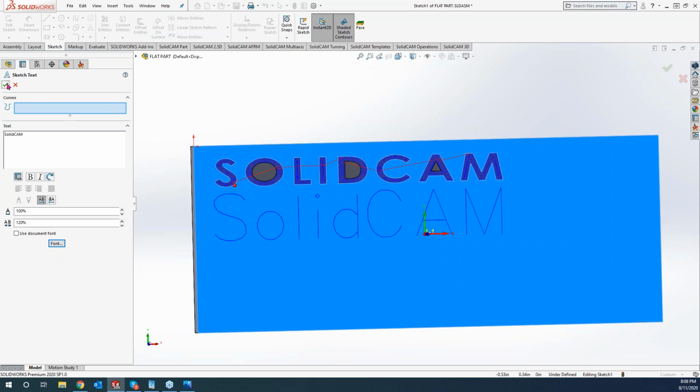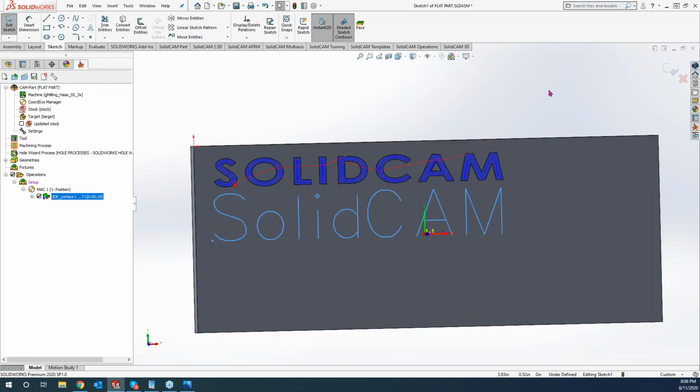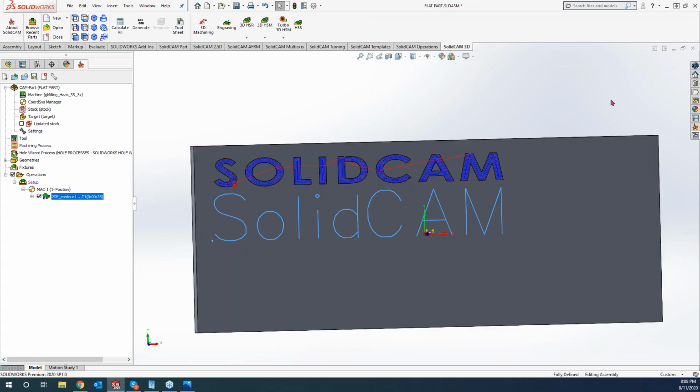Now, once we have that sketch in there, one thing to remember is make sure you're fully exited out of the sketch, because right now we currently have that sketch active. And if we go to try to grab that sketch inside SolidCAM, it's not going to see it just because that sketch is still active and going. So I can hop out of there real quick, and you can see my sketch turn from a blue to a gray at this point. And now we can go to our engraving again.